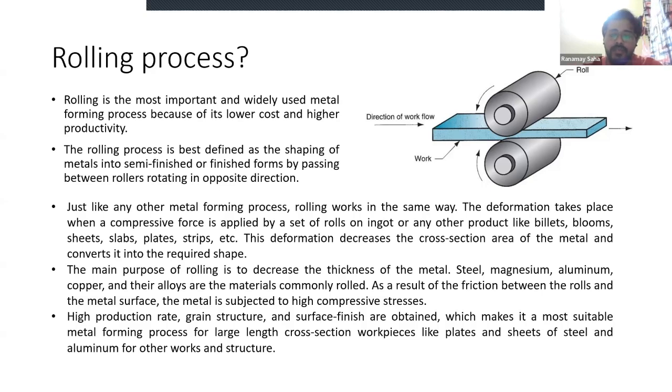So that way you can reduce the thickness of the sheets through the rolling process, but the width of the sheet is considered to remain constant in the rolling process. Okay? So by width, I mean this width of the sheets. W actually remains constant. If you take W1 initially and W2 finally, then W1 happens to be equal to W2 in case of the rolling process.